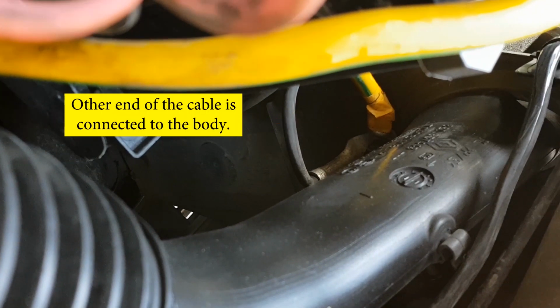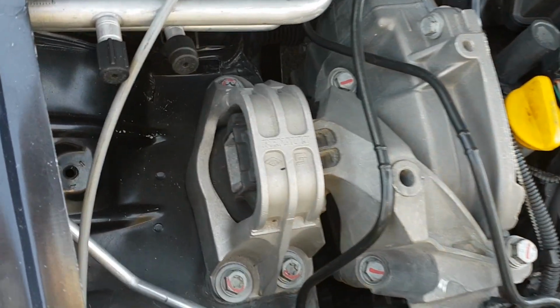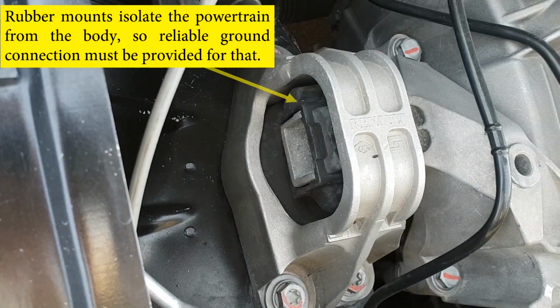Also, since the powertrain is insulated from the body by rubber mounts or bushings, which are kind of insulators, at least one ground strap is required to connect the powertrain to the negative.